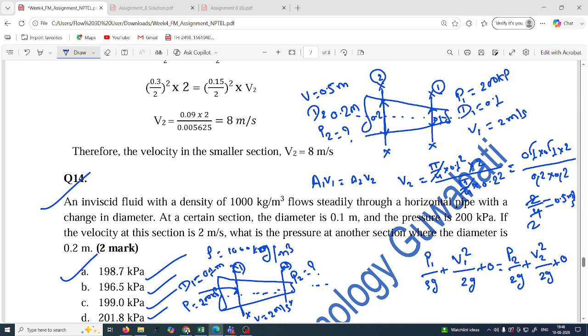meter per second. So velocity here is 0.5 meter per second. One thing you can remember, you can interpret it: area is increasing, velocity is decreasing. As you can see here, area means diameter. We are talking about a circular pipe. Diameter of the pipe increasing, velocity is decreasing. As you can see here, diameter from 0.1 to 0.2 means 2 times.